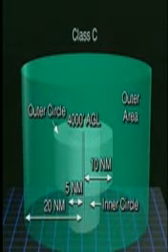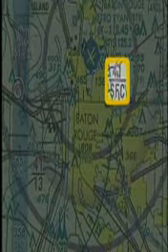Before you can operate within the inner or outer circle, you must establish and maintain two-way communications with ATC. While not mandatory, you are strongly encouraged to establish and maintain communications with ATC when operating within the 20-mile outer area. To fly within Class C airspace, your aircraft must be equipped with an operable Mode C transponder. This requirement also extends up to 10,000 feet MSL above the lateral limits of this airspace.